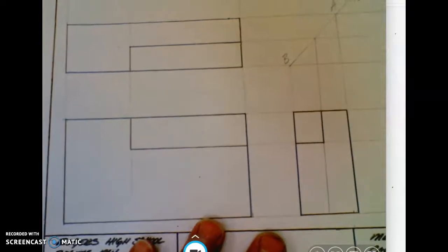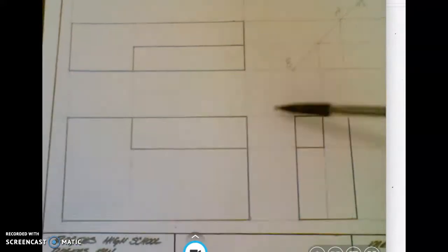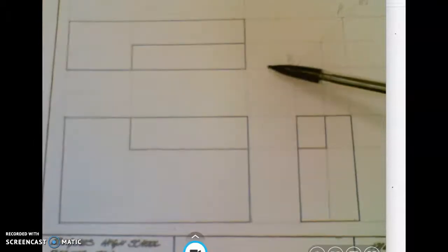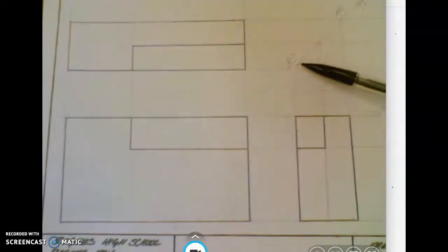This is what drawing number 1 looks like. Completely darkened in solid object lines with 1-inch spacing in between the views, showing all necessary construction lines, multiple locations, as well as showing that 45-degree mitered projection line.